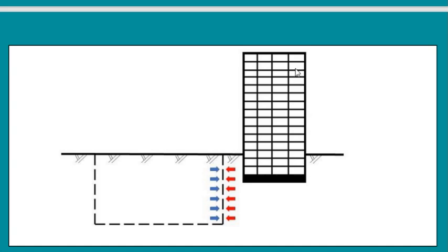So this is exactly what is here. This is a building, and this is my new site. I want to excavate here to reach this bottom layer. If I excavate here, what will happen? The small portion of soil here will collapse, and my building may collapse. You may find that the soil takes an angle of 1 to 1, or 1 to 2, and everything on top will fall.